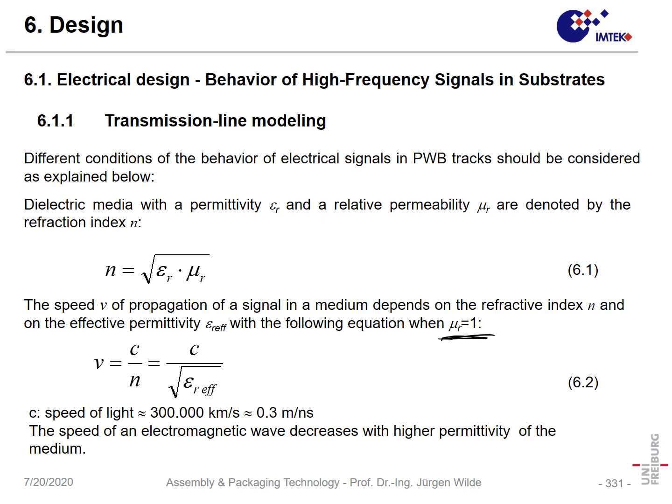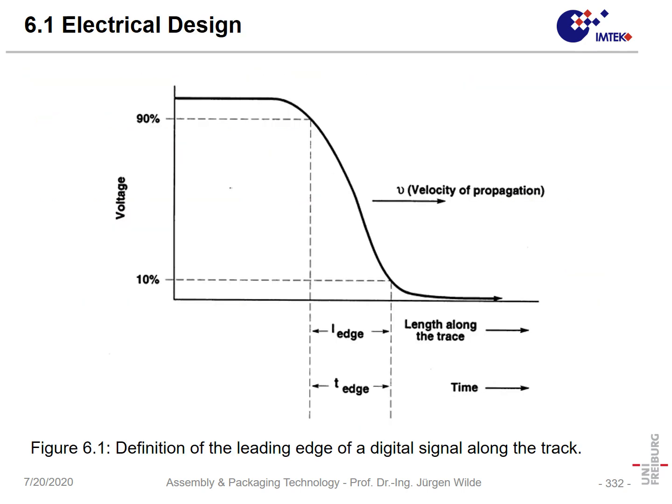And that means when you have a computer operating at a very high frequency, somewhere in the gigahertz range, where the cycle time is 1 nanosecond, you can have already effects of the speed of that signal, and the running time of a signal, or the so-called time of flight of a signal, will have an effect.